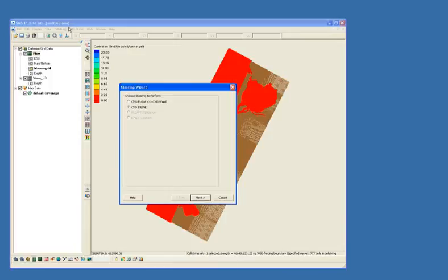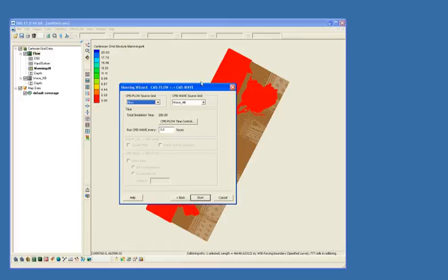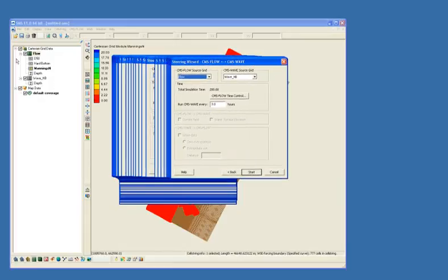And so since I had specified in the model control the implicit model to be used with an implicit time step of 600 seconds, I'm just going to choose CMS inline and click Next, and there's a few options for you to choose. Depending on what you have loaded in the data tree, you could make sure that you're using the right flow grid and the right wave grid, and you'll tell CMS to run every X number of hours.